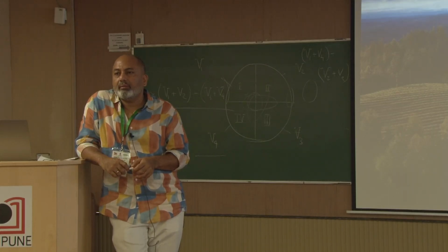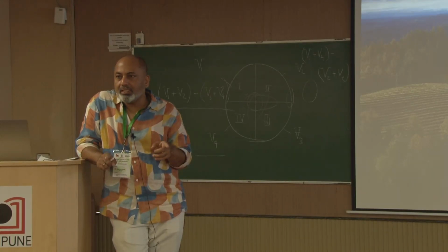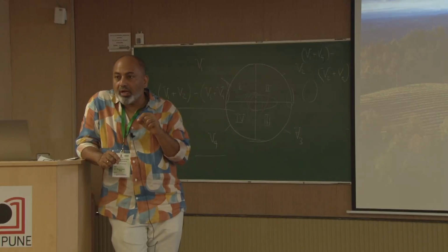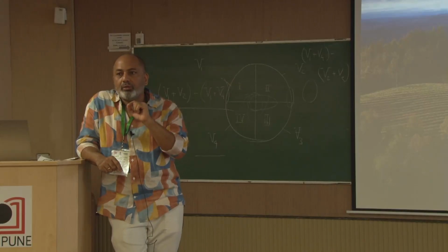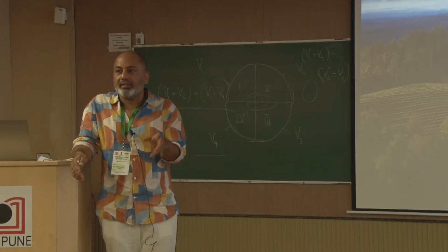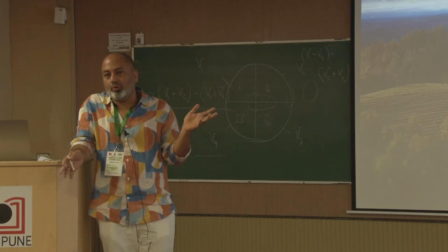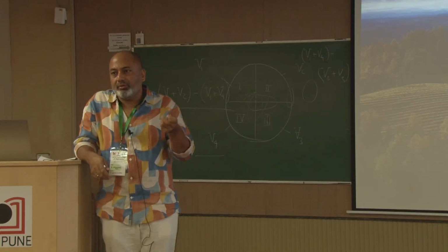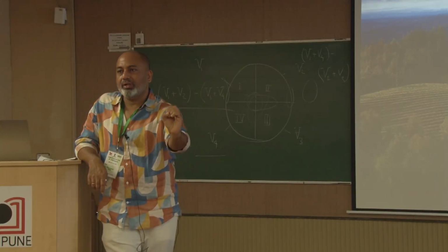Other than the laser, can there be other sources, for example LEDs, with a little bit of optics? Yeah, they can be used, but lasers are nice because they're coherent. The light has to travel a distance from the laser all the way to the detector, about 10 millimeters. If you use an LED, it will spread, and by the time it reaches the detector, the cross section of the detector is small, so a lot of power will be lost. The nice thing about a laser is that it is coherent and collimated, so it retains its power.